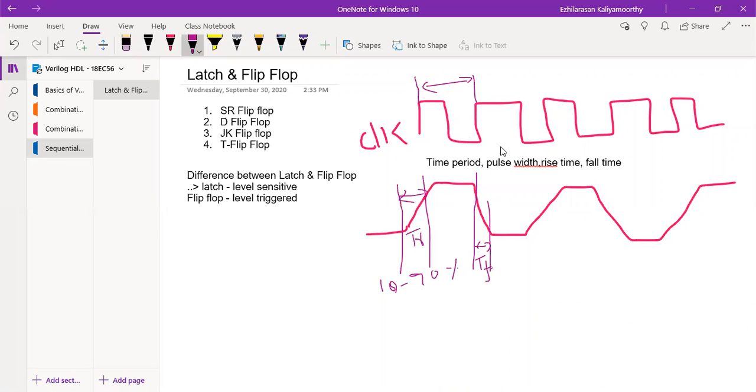So you compare these two. What is it here? It is a level. Exactly, there is a straight line here, right? Meaning the rise time is 0 and the fall time is also 0. Why? Because if I take the period like this, from 0 seconds, that is nanoseconds, I will consider this time as 5. Because here we have a level, and between this level it is the logical high value. From this portion to this portion, I cannot predict whether it is 0 or 1. It is a transition from 0 to 1. That is why I can say this is 5.